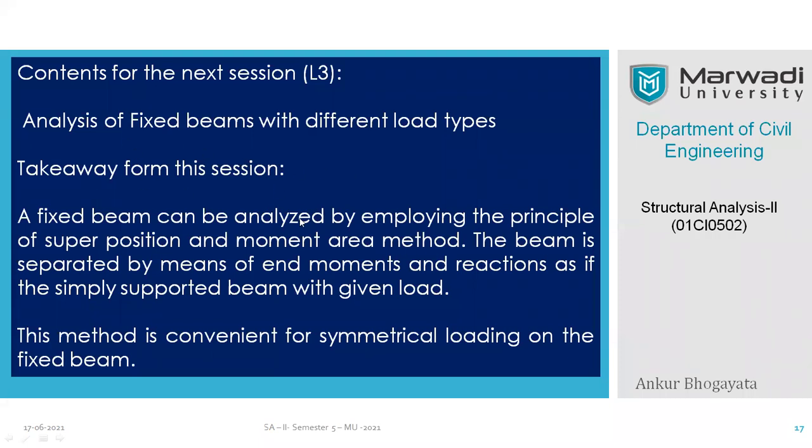So what is the takeaway of today's session? That means, what is a summary? A fixed beam can be analyzed by employing the principle of superposition and moment area method. The beam is separated by means of end moments and reactions as if it were a simply supported beam with the given load. Right? This method is convenient for symmetrical loading on the fixed beam only. Right? So likewise, you can see that we have come up with the first step, baby step, towards analyzing the fixed beam in the given standard loading case.